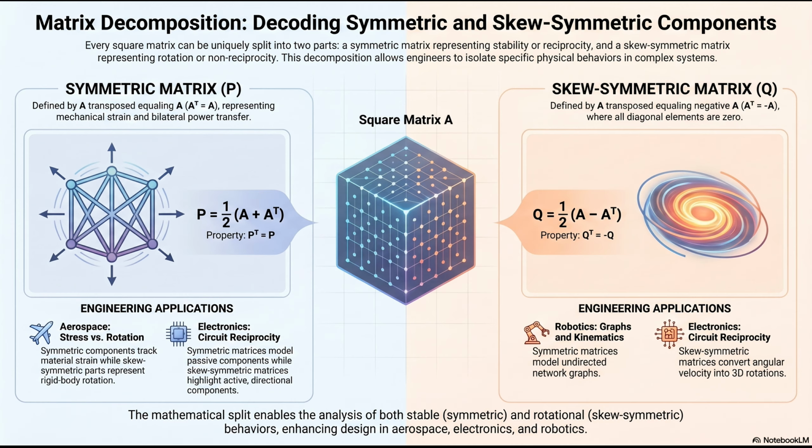To actually calculate the new position of the robotic arm's mass in three-dimensional space, that angular velocity vector has to be transformed into a matrix operation. Oh, I see. Specifically, it has to become a rotation matrix. And so the cross-product operator is the specific tool that makes that transformation. Yes, exactly. When you take the cross product of the angular velocity and the position vector, you are calculating the instantaneous linear velocity of that specific point in space.